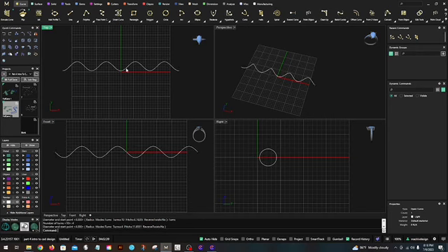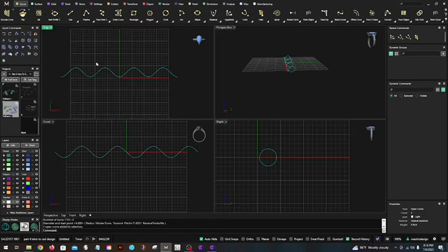So if I want this consistent pattern, but I don't want it spiraled or in a helix form, I can take that and type in the word project to C-plane, and yes, delete input, and it flattens it. See, it's flat to the C-plane.